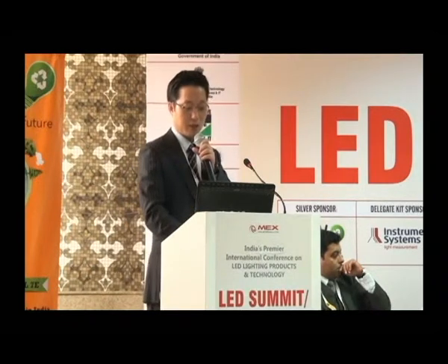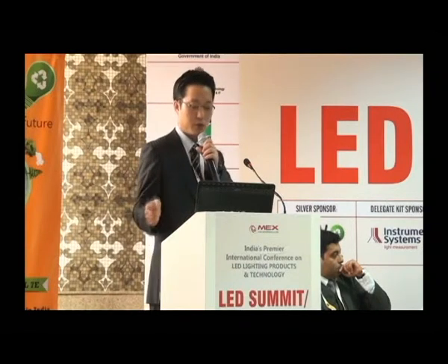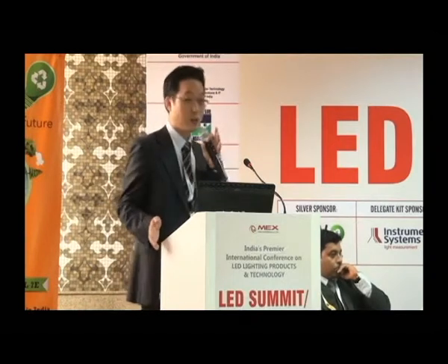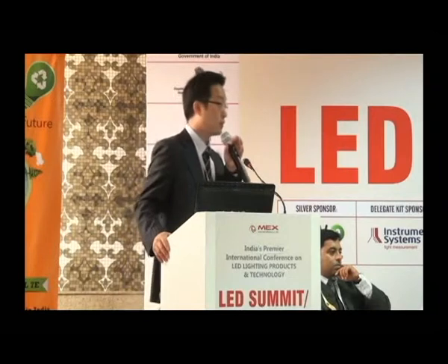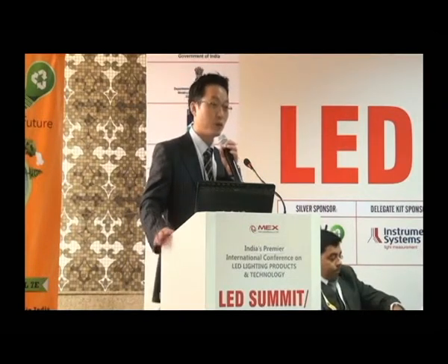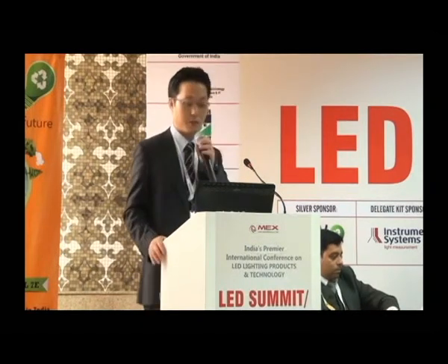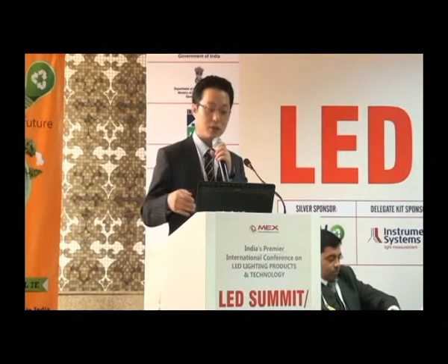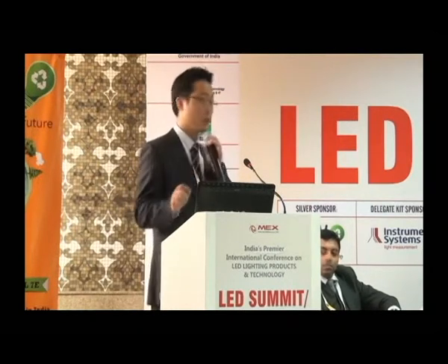But nowadays the trend is going more to injection molding because of productivity. If you want to make 1,000 or 2,000 lenses a day, stream molding is enough. But if you want more, 10,000 or 100,000, you cannot make LED lenses with the stream molding process. That is the reason why lens customers are moving to the injection molding process.